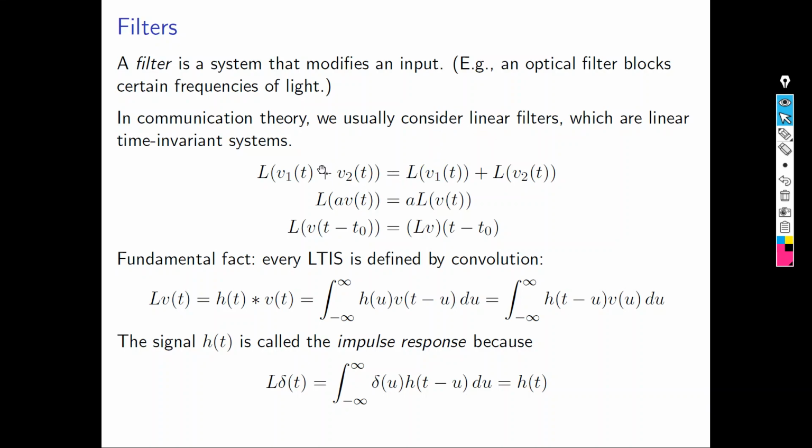So basically you take the Fourier transform of each one and then you sum all of them. If you multiply the signal by a factor alpha and take the Fourier transform, you can take alpha out of the Fourier transform. And if you shift it, you can take the Fourier transform of the signal and then take the value at the shift. So these are the properties that apply to a system that's called linear time invariant.